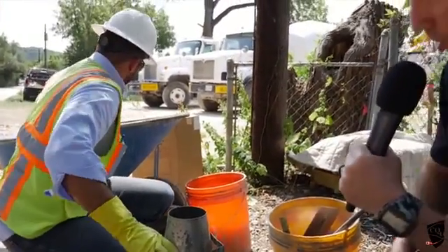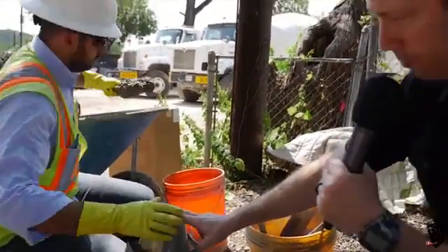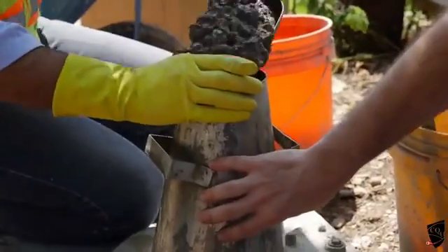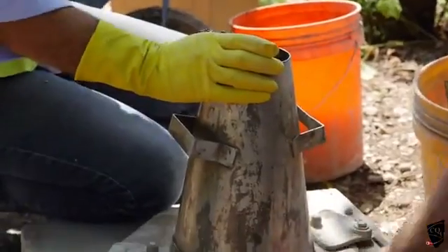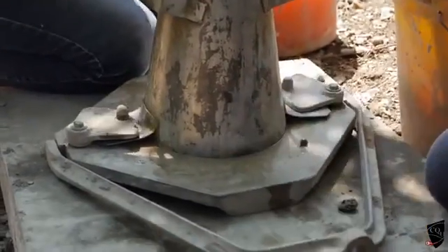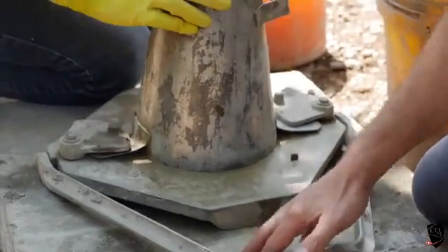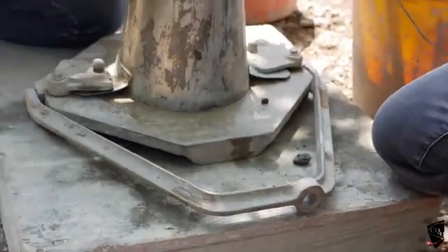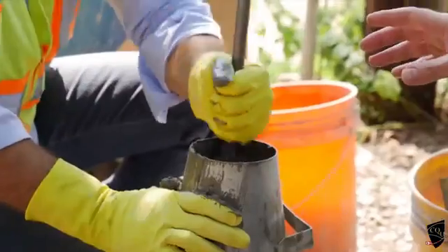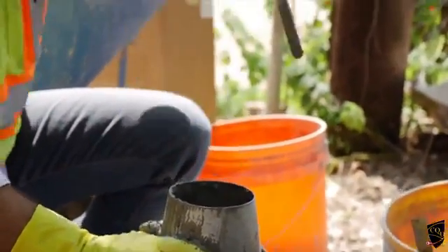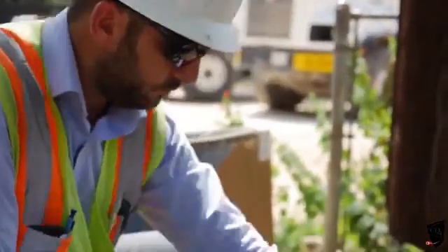So he's going to fill this cone. Now this is 12 inches tall. What you saw was he put the cone in water first just to make sure the concrete wasn't sticking to it. He also put a little bit of water on the bed so the concrete wouldn't stick. He's got it on a level surface, which is this plywood that he's using on every job. He's a third-party testing company that we use so that I can hand our clients a third-party certification as to what my slump tests are.